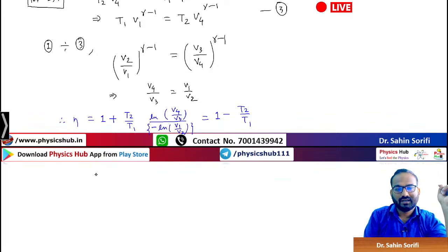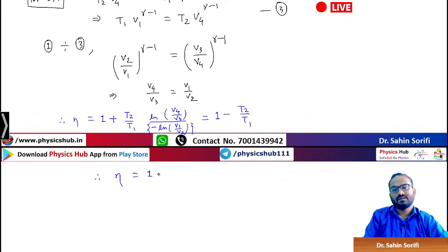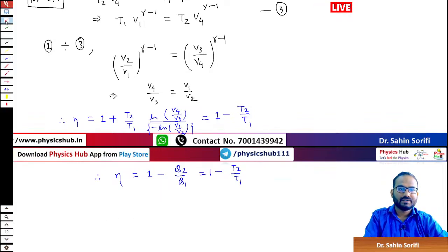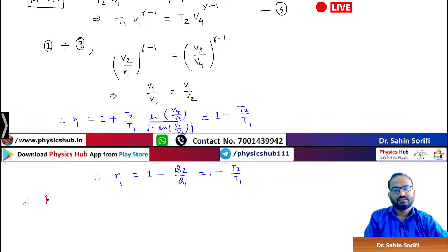So we can combine this result as eta is equal to 1 minus Q2 upon Q1 is equal to 1 minus T2 upon T1, and hence we can conclude that for a Carnot cycle, Q2 by Q1 is equal to T2 by T1.